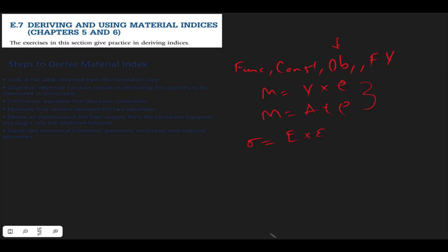You know that the formula for strain is equal to change in length over original length, L0. You have to find a way. Let's say the length that you're talking about is the thickness of the material. Let's just assume that, and say strain equals change in length over thickness. Let's say L0 is the thickness. So right now your stress will be equal to E times change in L divided by thickness. Let's just say that's the case.